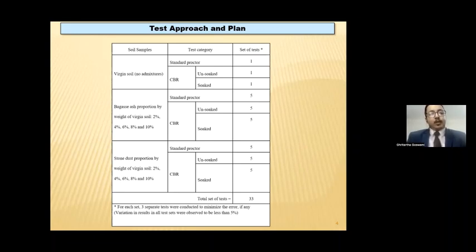While standard Proctor test is suitable for ordinary transport infrastructure, pavements for heavier traffic loading, for example aircraft and heavy trucks, demand modified Proctor test. In this study area, the traffic loading is much lighter and hence the standard Proctor test has been followed.